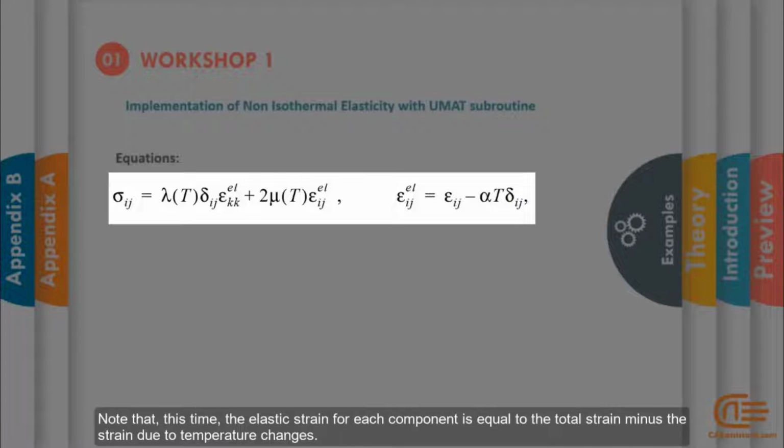Note that this time the elastic strain for each component is equal to the total strain minus the strain due to temperature changes. Therefore, we see a temperature-dependent term in the stress and strain equations compared to the previous basic stress-strain relations.